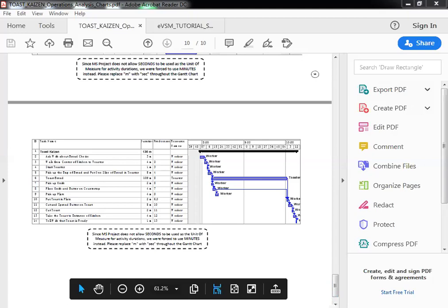So the first spreadsheet here, you can see, these are all the steps, right? These are all the individual steps which were done in the order that they were performed. These step numbers 1 through 30 will come from the flow process chart, but the activity sequence, since he has to draw them in a certain sequence, has start time and duration. So start time plus duration will give you the finish time, right?